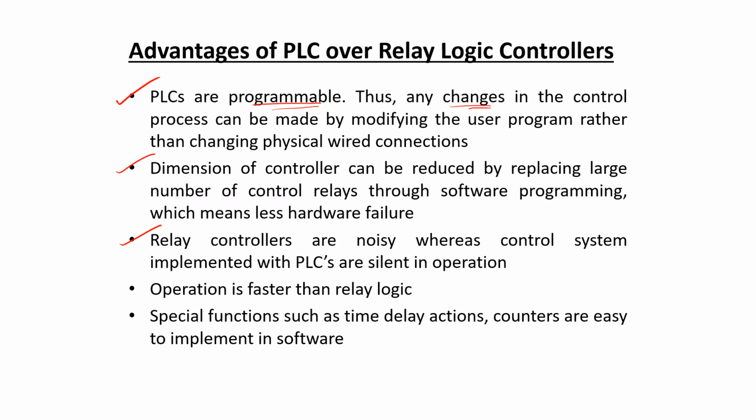However, the PLCs, which are obviously based on solid state technology, because instead of using electromechanical relays, solid state devices such as ICs or transistors are used to manufacture the PLC. So the PLC also provides noise-free operation. And also the solid state devices provide faster response or faster operation compared to the relay.